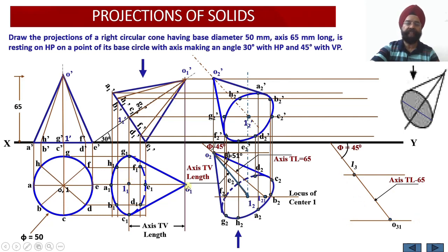I know the apparent length, which is equal to O1 1 dash. It is this arrow. So this arrow I am going to draw again corresponding to the apparent length. And having worked out the apparent length, O3 will be worked out over here. So point O3 will be there. This is the apparent length. The moment I get the apparent length, angle beta I can measure. Please see, angle beta apparent is once again equal to 51 degree. And there will be no difference in the angle beta in this case or in this case.